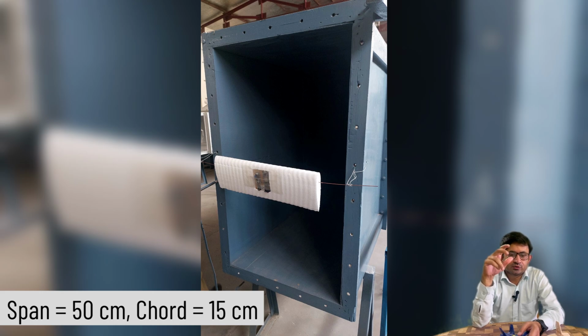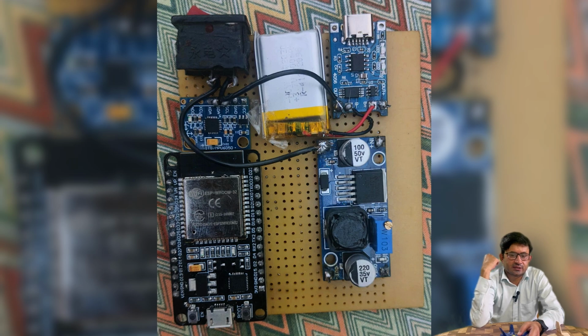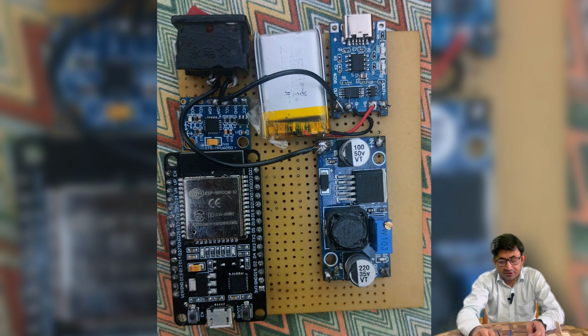Here you can see the airfoil which we have used, NACA 0027. You can use NACA 0012, any airfoil you can use. We have used a symmetrical airfoil, and we have instrumented this. These are the instruments we have used. They are always readily available in the market. Sensors like an accelerometer, controllers like Arduino and all, everything is readily available. You can purchase them, and you can set up this experiment for less than 500 rupees. So it is very good.